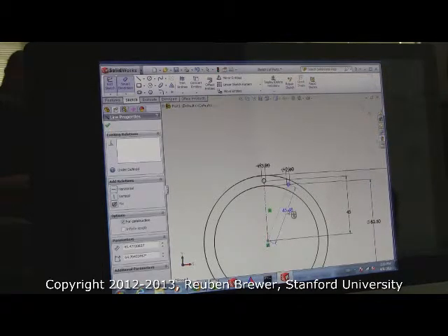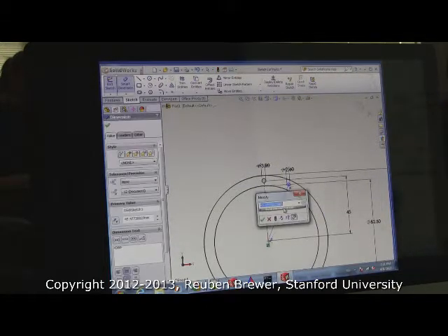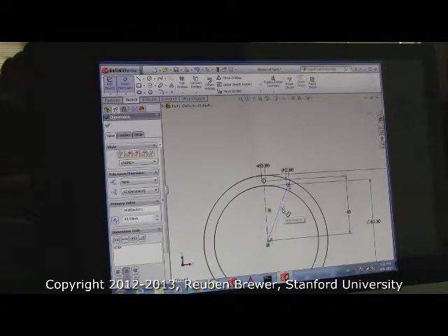So Smart Dimension. Now click the line, but don't click again. Let's play with this for a sec. You see how right now it's in the right direction on my screen? This is a radial dimension. Up here it's a horizontal dimension, and over here it's vertical. So SolidWorks allows us to do basically whatever direction we want. If you're trying to go along in the direction of the line and you can't, you just need to wiggle your mouse until you go to a position where it can. So make that 45 in length.